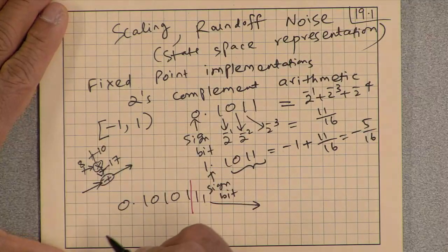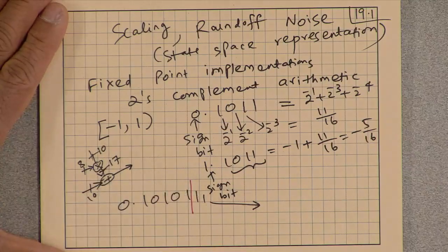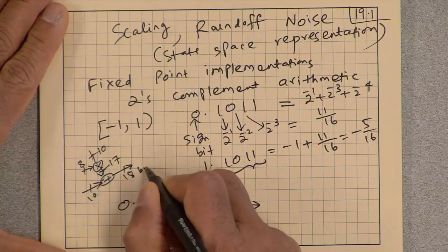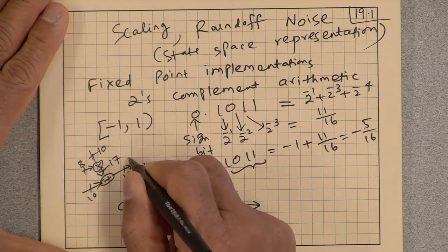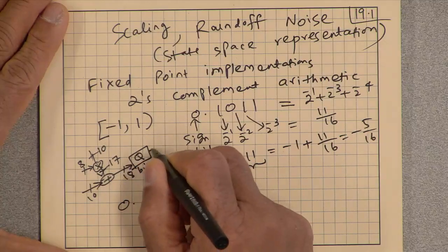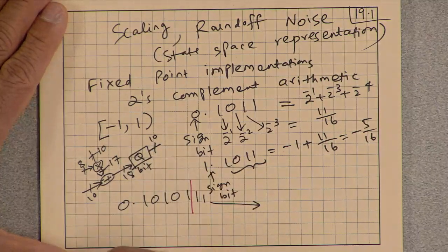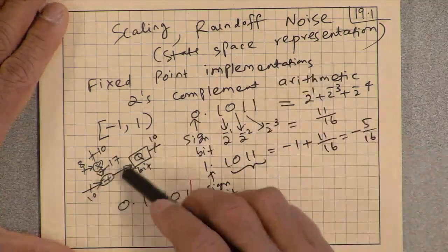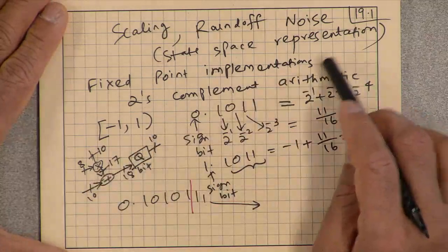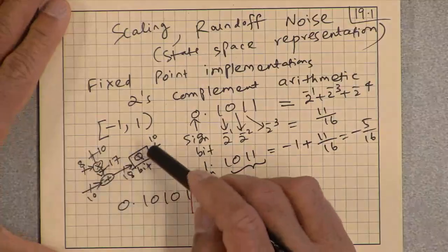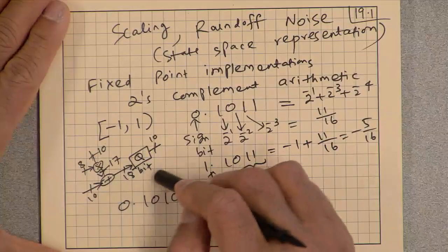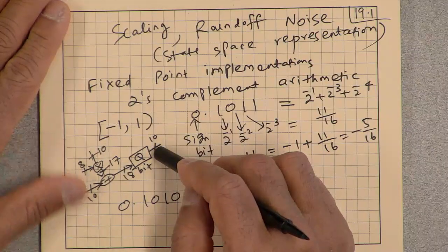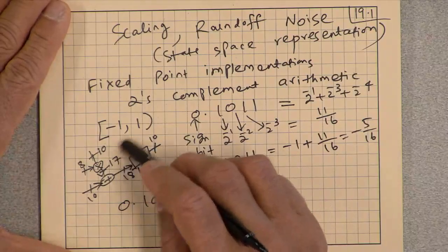So this would be 17 bits, and let's say this was also 10 bits, then this would be 17 plus 1, it could be one more bit, 18 bits. And we may be interested in reducing that, somehow quantizing that to 10 bits, because we may be interested in maintaining a so-called fixed width in the whole system. So the signal word length may be 10 bits everywhere. So when the multiply add computes, it computes the complete result, which in this case is 18 bits, and then we represent that using 10 bits by some kind of approximation.